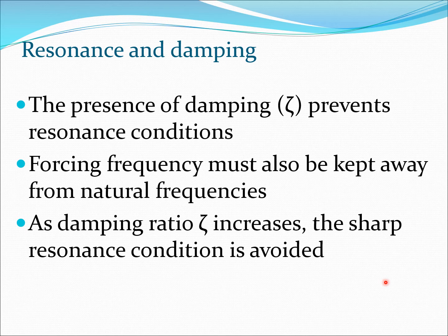So some of the things we learned here: number one is that the presence of damping prevents resonance conditions. So that is something to keep in mind, that damping is very beneficial. And we will see, as far as helicopter dynamics is concerned, damping plays an enormous role in keeping these machines safe and flying and in bringing down vibration levels.